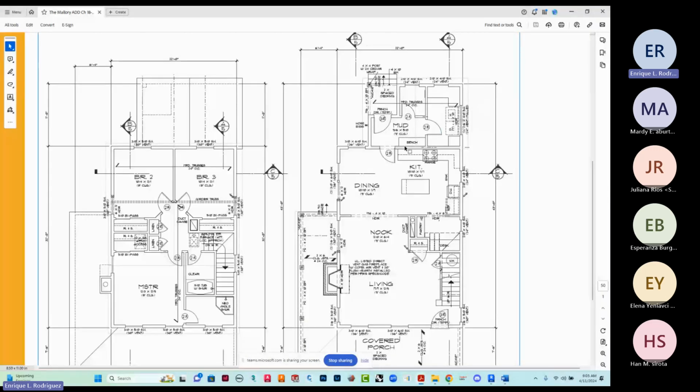All right, so they do give you some room sizes in here to work with. And as you can tell, the mudroom, it says, is 5 feet from the outside edge of this wall to the inside edge of this wall. And the reason I'm saying that is because typically the dimensions that you have in here are inside clear dimensions. They don't include wall widths, etc. Most plans will have those dimensioned clearly so that you know either what the width is, including a wall, or inside dimensions, and they'll dimension the wall.